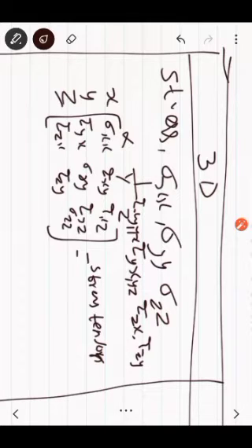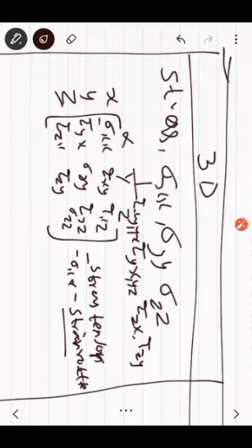The sigma x, sigma y, everything will be obtained from strain rosettes. So this is the importance of strain rosettes. The strain rosette is a strain gauge that is fixed in the x direction, y direction and z direction. The change in length with respect to the original length is the strain, and we multiply it with the material property, Young's modulus, and we get the sigma.